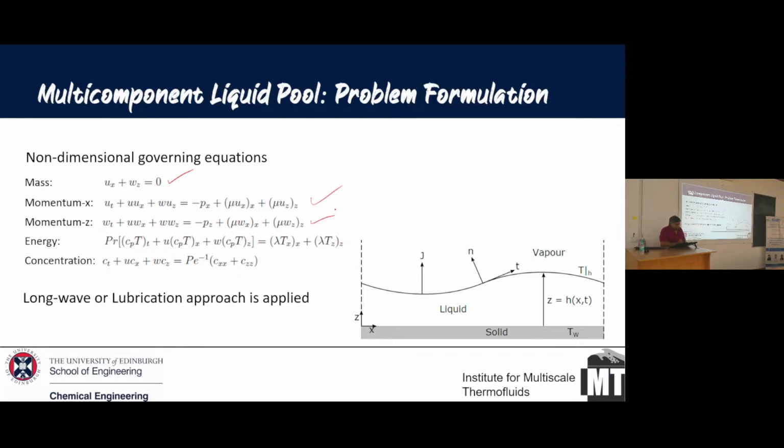So you've got the momentum equation in z, and you can notice that I have not done anything with gravity. I have not done anything with gravity because this is such a thin film, I'm not really bothered much about it. In fact, this is not completely correct. When you have evaporation, you will have buoyancy effects come into the picture. I'm ignoring those effects.